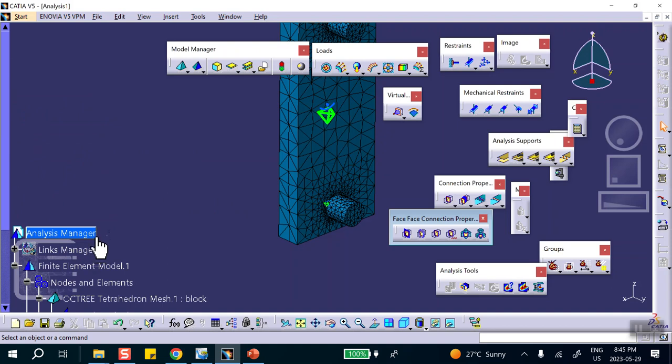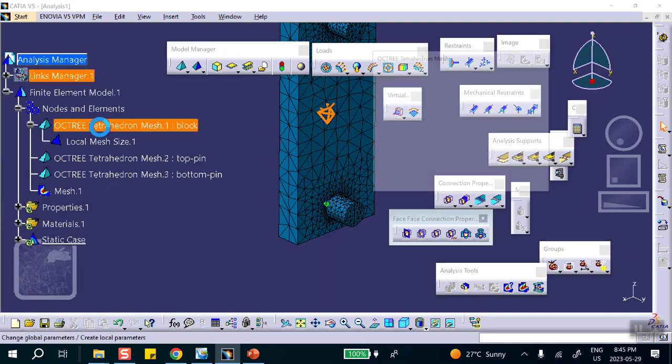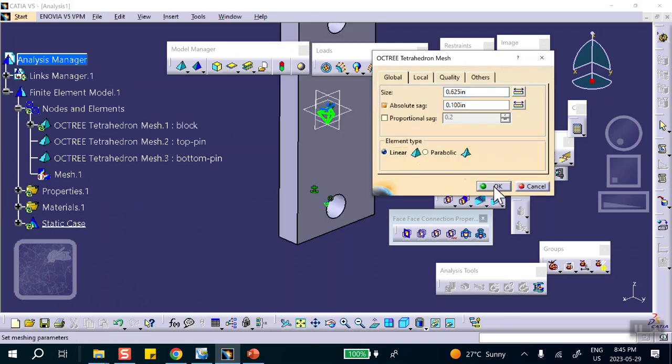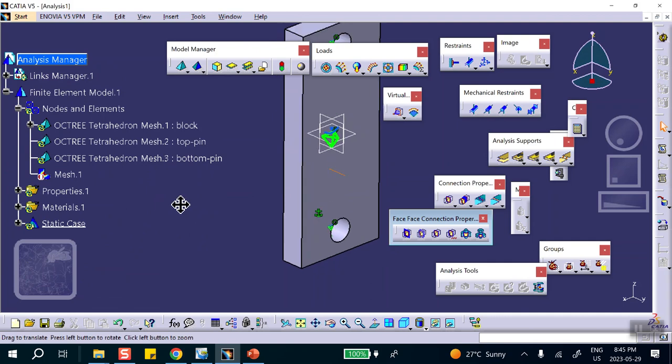So, okay. So let me go here, make sure that it is actually linear, so that I can rotate stuff, I can move things. This is where on the test, unless you're specifically asked, do not use parabolic elements. Okay, good, very good.